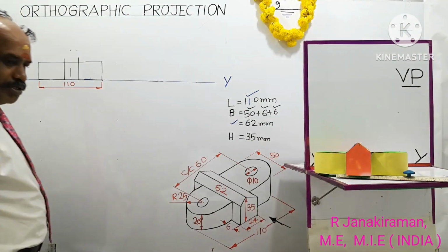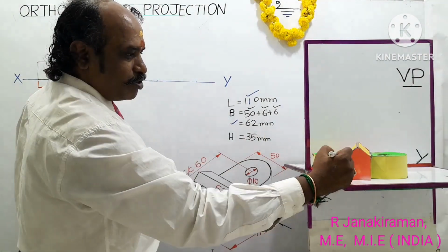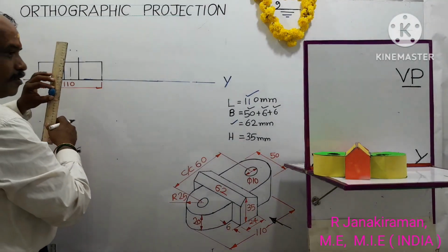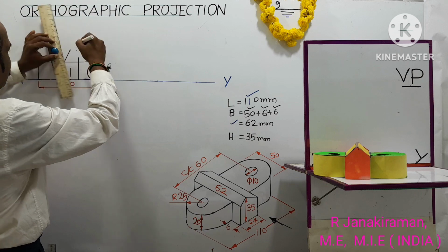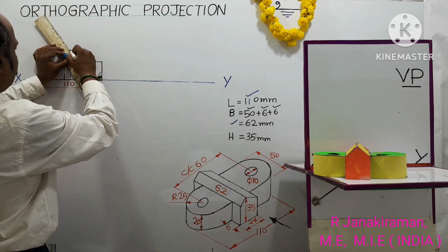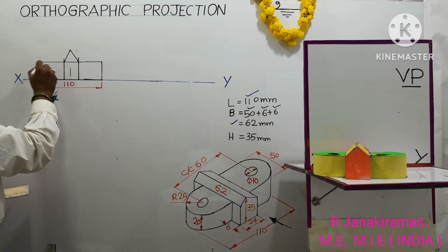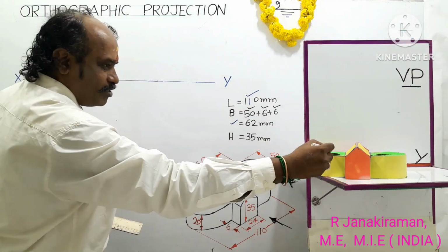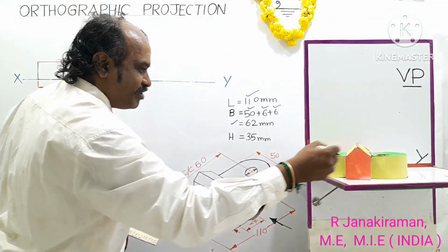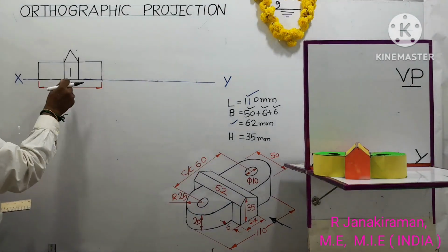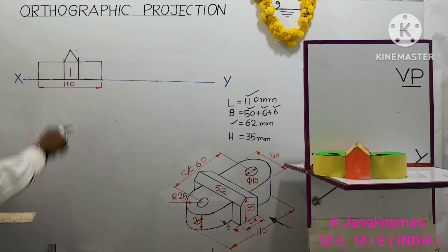So now I'm going to join those points obtained, forming the triangular part. This triangular portion is to be constructed. So join the base edge top surface with the topmost corner. Okay. So this corresponds to the front view. That is, this is the top surface, shown green in color. It's merged, forming a single top edge, right side and left side, and is joined with this 24 mm distance. So this forms a triangular portion, shown red in color.